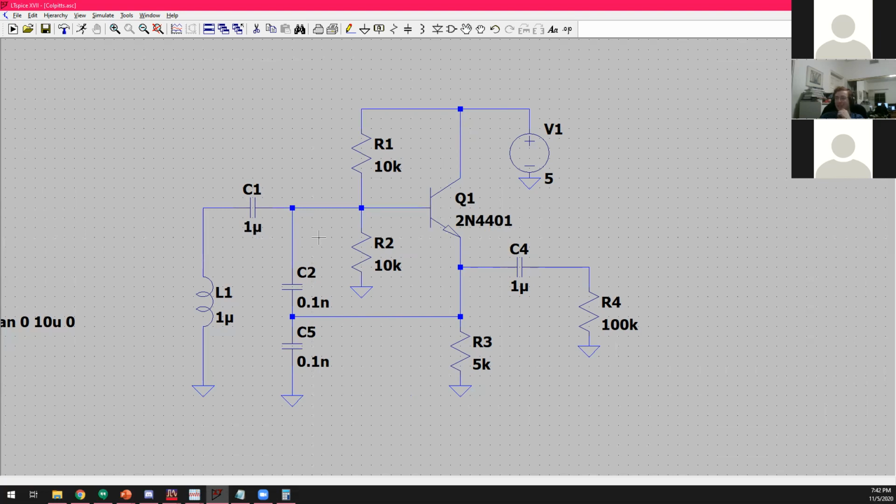No difference, assuming you make this capacitance big enough. It turns out that there's another type of oscillator that's related to the Colpitts oscillator called a Clapp oscillator. And what you do is you just make this capacitance a lot smaller, which makes it more significant at the oscillation frequency. And you can control the resonant frequency by changing this capacitor, but here I'm not doing that.